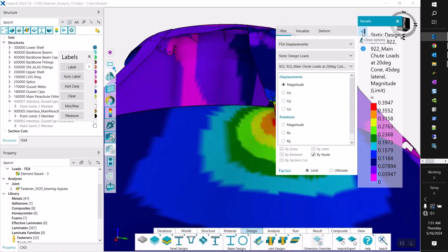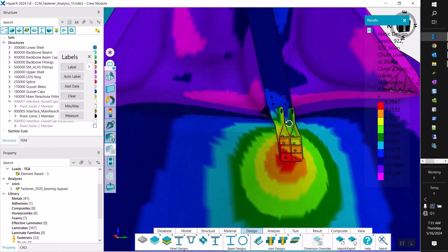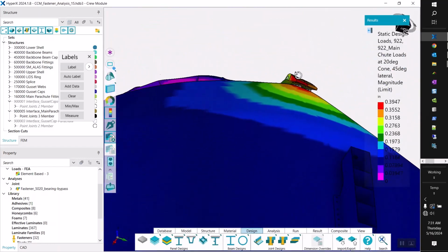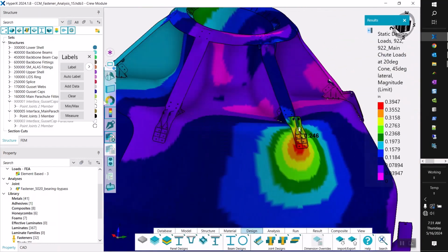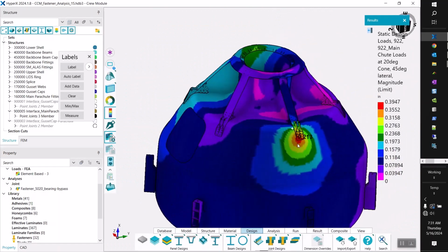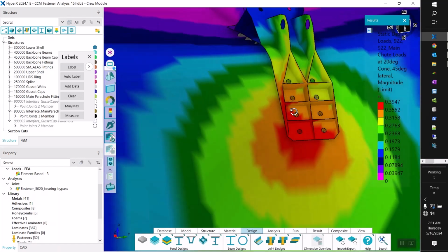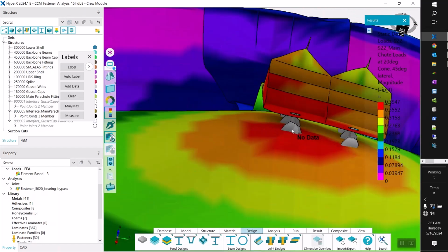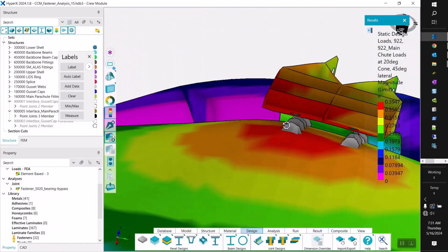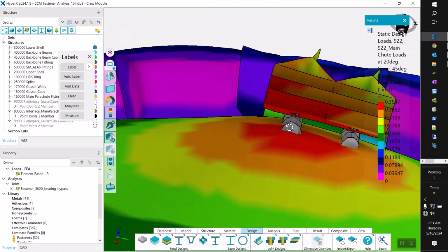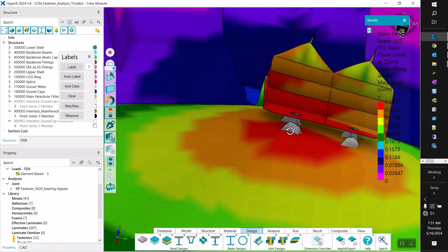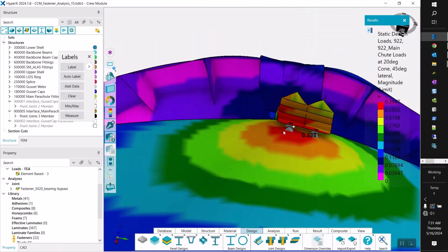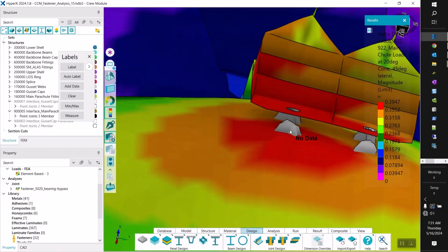The main parachute fitting is being pulled very, very hard on this one side, and the fastener that we found to be critical was this fastener here. You can see kind of the heel toe effect going on, where not only is there tension load, but there's shear, and then the heel toe effect putting additional tension in this spring.